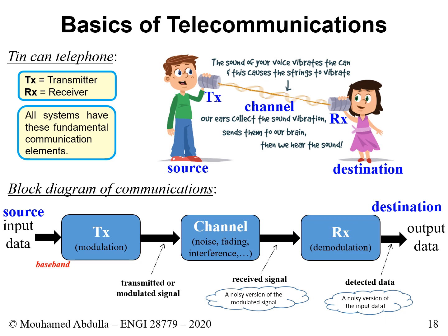one other terminology that I should mention is baseband. When we generally look at signals entering a modulator, we refer to them as baseband signals. These are signals that have a center frequency around the origin. And signals that operate after the transmitter are referred to as passband signals. And of course, since you're still in the channel, the signal that you detect at the receiver is also a passband signal, and the signal that you get at the output is a baseband signal.